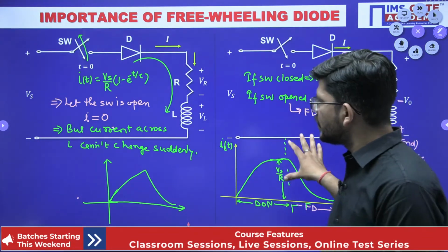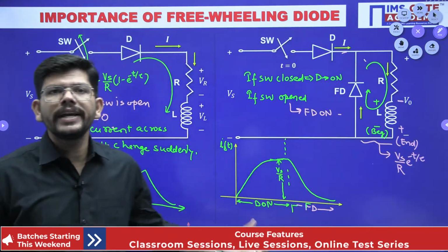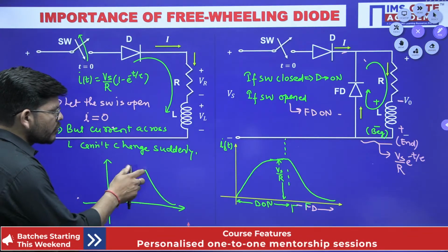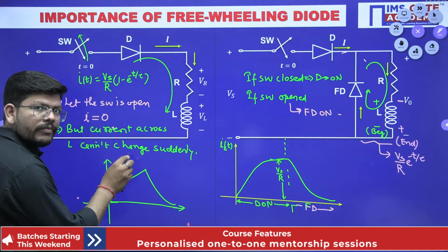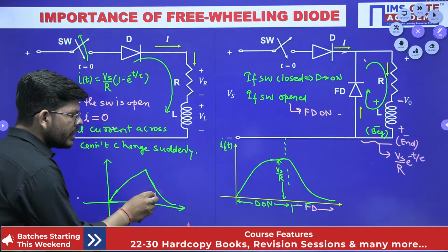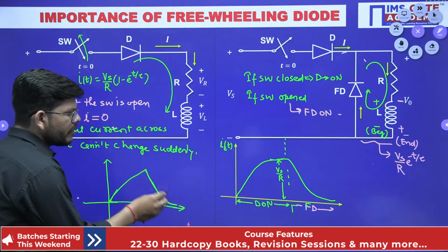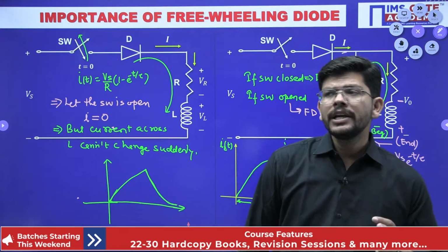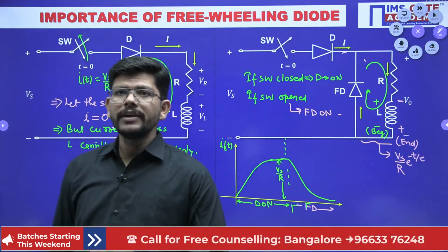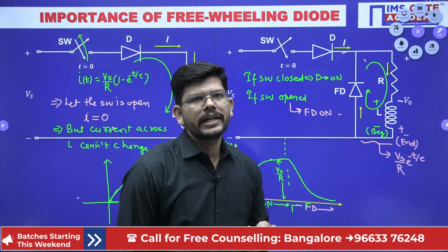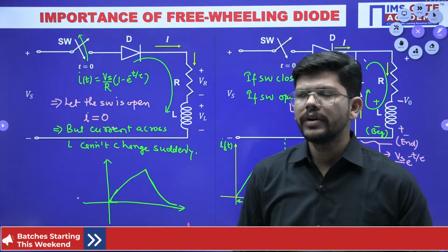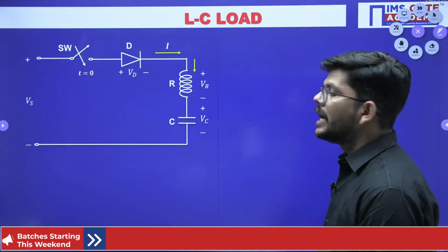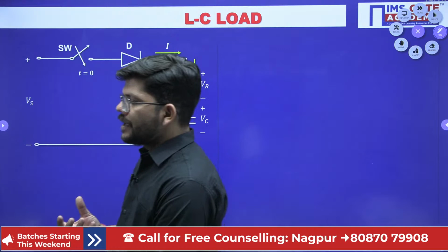This is coming because of the factors we have analyzed here, isn't it? The current across an RL circuit first reaches a maximum value, and then when the freewheeling action takes place, it comes back from that maximum to 0. This is very important. You are going to see these patterns very frequently in inverters, rectifiers, choppers, everywhere.